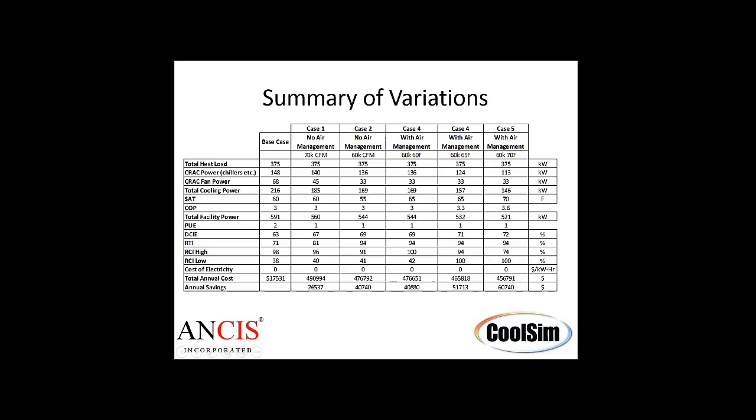And then if I jump up to even higher, this one's at 70 degrees Fahrenheit, it falls off altogether to 74. So again, here's the optimal operating point, right here, 65 degrees, 60,000 CFM, and if I can get the system to operate that way, my coefficient of performance improved because I went up 10 degrees, so I got another 10% out of that. I went up 5 degrees, got another 10% out of that. 10 degrees will get you roughly 20%, so that feels just about right.